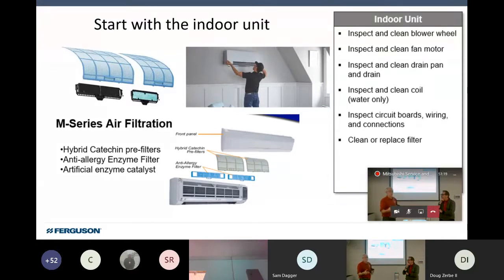So blower wheel may need to be cleaned. We're going to actually get into cleaning a blower wheel and the right way to do it. So inspect and clean the fan motor, no oil ports. That's like oil ports are gone from everything anymore, but that's my mindset from years ago when every motor had to be oiled. So it all just pops up in my mind.